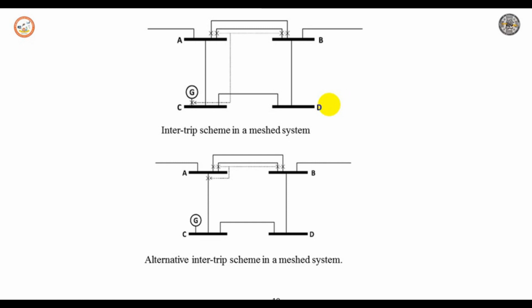Moving on, as a last topic, we will see the losses. Estimating the increase or decrease in the losses due to the introduction of distributed generation may require more detailed studies. An increase in the losses can be compensated by a reduction at another moment in time or at another location. So what matters here is the total losses over all the feeder sections, integrated over time.